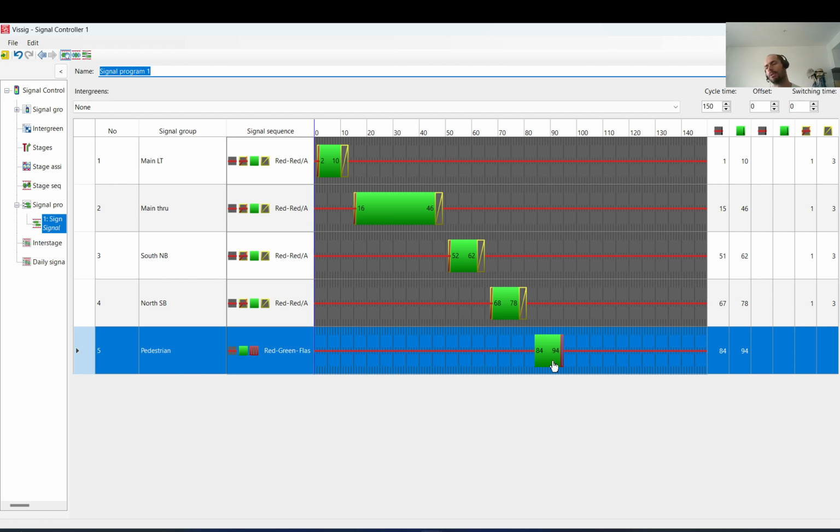You need to calculate how much the walking time is, so like the longest distance they walk, and by using an average walking speed, you can just calculate it. I'm going to just use approximately 10, and I will leave a very long intergreen after, because pedestrians may step out later.